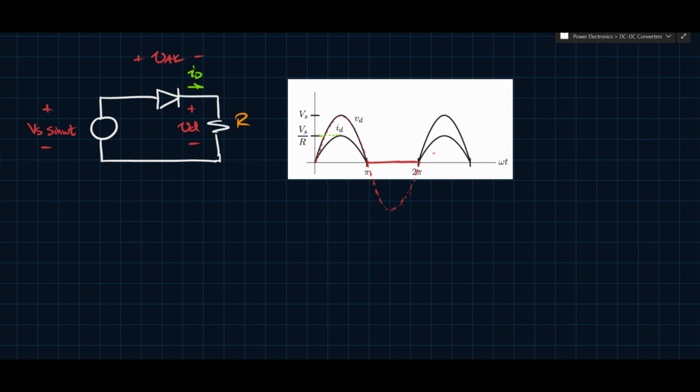It was, historically speaking, because back in the day they used to use vacuum tubes for this type of stuff, and vacuum tubes had really large voltage drops, so you wanted to minimize the number of vacuum tubes you used. And so in that case, having only one diode, or vacuum tube acting essentially as a diode, was beneficial. But nowadays we have much more elaborate rectifier topologies because we can afford to, because with the popularity of silicon, you have much lower voltage drops across these devices.